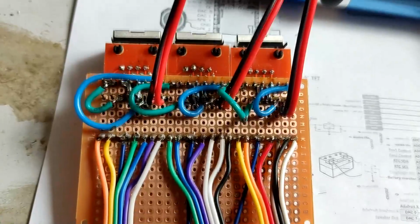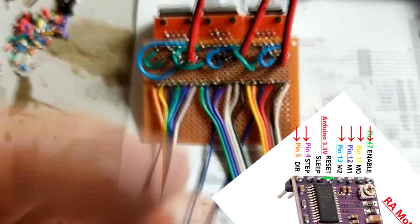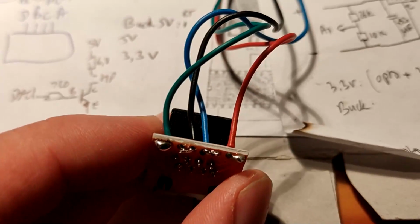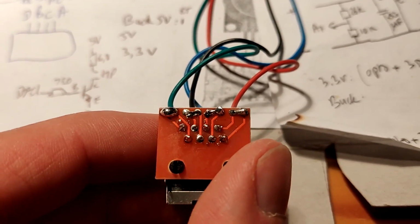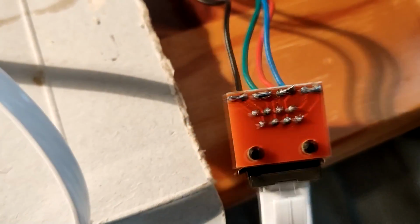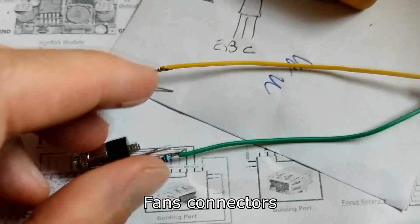Here we have all the pins on the side of the driver connected with the DuPont cable end. It will help us when we're going to use a breadboard. So I soldered the 4 wires of the motors to an RJ45 connector 2x2 as we've seen before, to make the current go through 2 wires, and then later I inverted some wires so I'll let you see the final version. The next part is the making of the fan connectors.